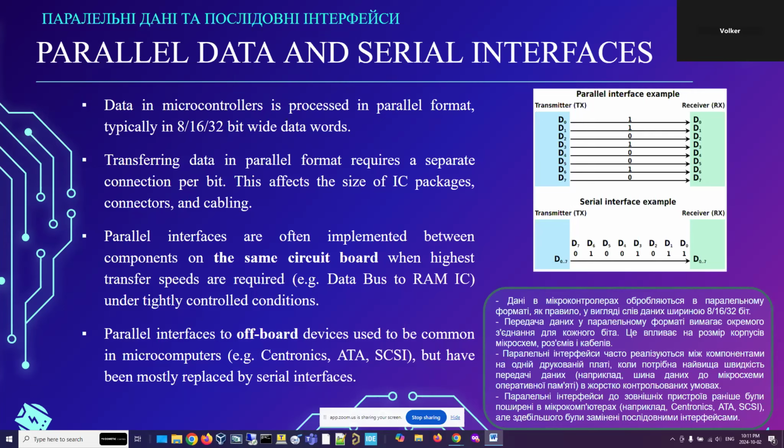For systems that have 64-bit or 32-bit parallel buses, more and more of those integrated circuits are switching to a different type of package, which has the connections under the chip. Those are called ball grid arrays, BGA packages. One issue with these BGA packages is that they're difficult to solder and desolder, and they're also difficult to test. Usually, one requires